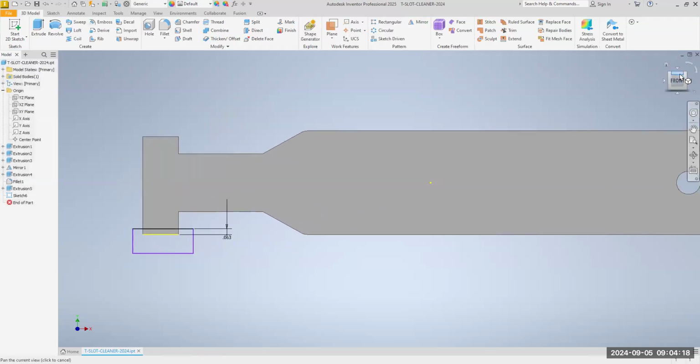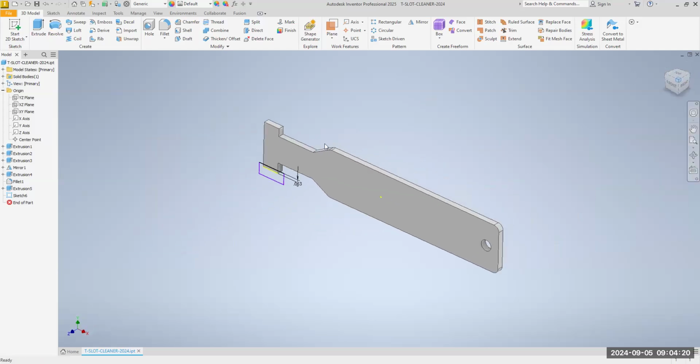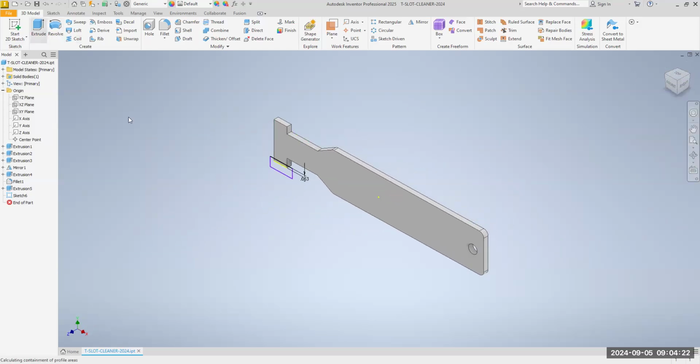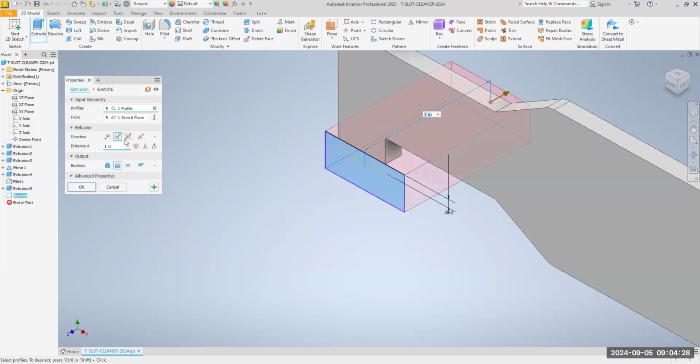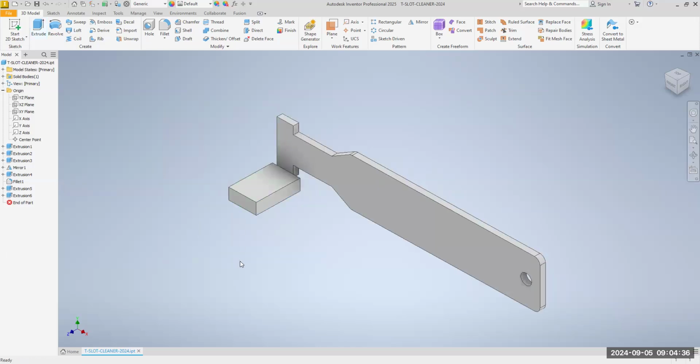and I'm going to get into the isometric view, and I'm going to extrude that, but I'm going to do it in the opposite direction because I want to cut material, not add it. Let me show y'all what happens if I do this. See, I don't want to do that. That would not be a good grade. Okay. So I'm going to hit the undo here.